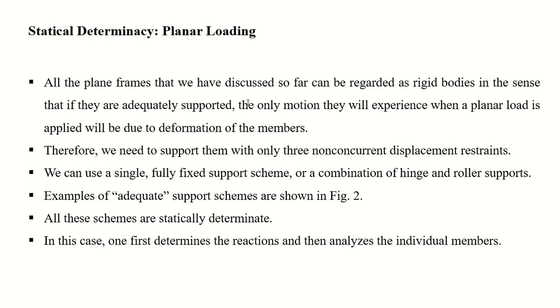Okay, the only motion they will experience when a planar load is applied will be due to deformation of the members. So if force is applied on a frame, then the deformation caused by that load will be the only motion that these frames will experience. Therefore, we need to support them with only three non-concurrent displacement restraints.